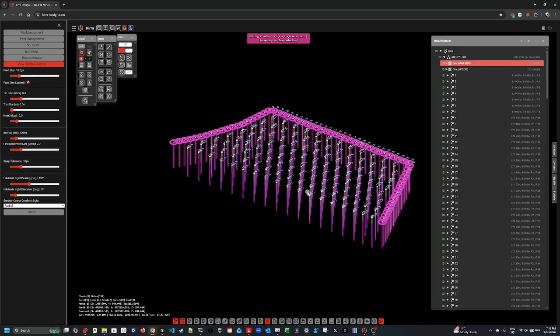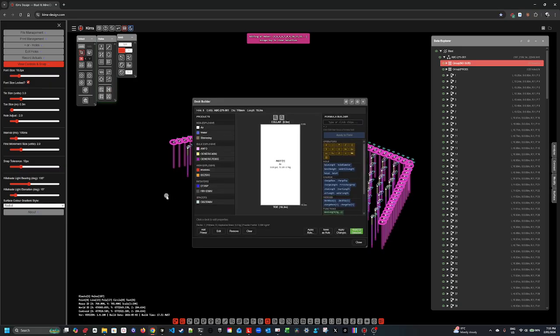And then we want to add some charging to the subdrill. So now we've selected those, and we do the same with our deck builder. And let's say our buffer holes are going to be a different product. They're going to be ANFO. So we're going to drop that in here. ANFO, we've got a bit of an air gap there. So let's deal with that now. Remove deck 3. ANFO, let's say we're going to have an air deck in there, yeah? So we'll put stemming at the top. Oh yeah, 2 meters, yep, edit the deck.